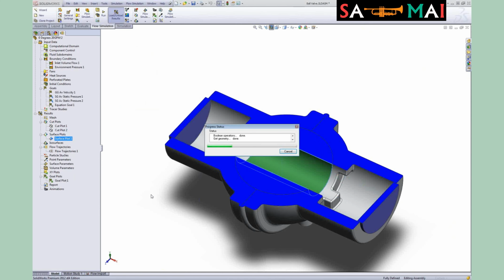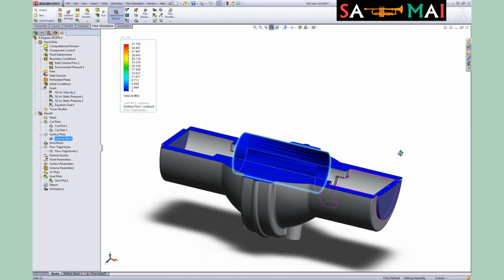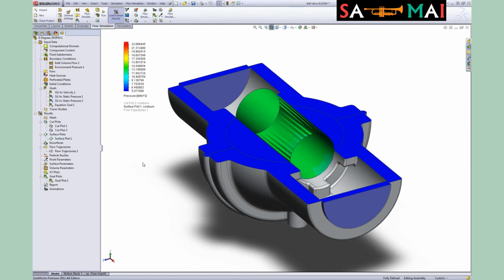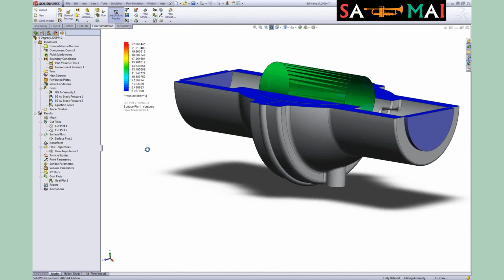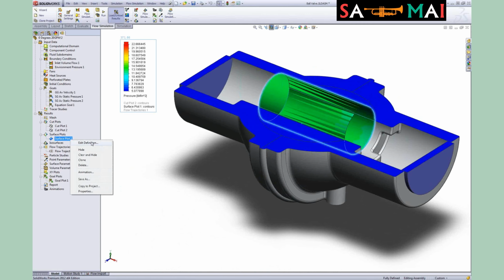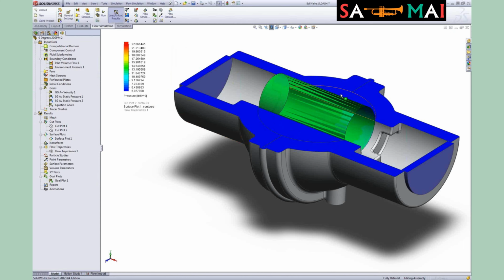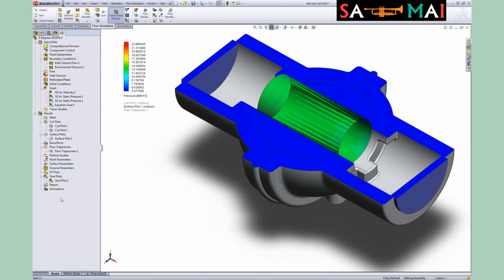You can also look at what are called surface plots. So I looked at the internal surface here. One of the things with the internal surface, we can change this to pressure. So we can see the pressure offset. You saw that the velocity was 0 at the wall. Essentially that is because it is at the wall. That is stopped there. We can do an offset and increase this in and see a little bit different change in pressure there.